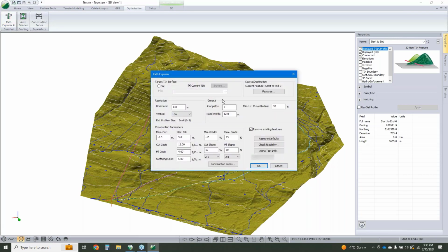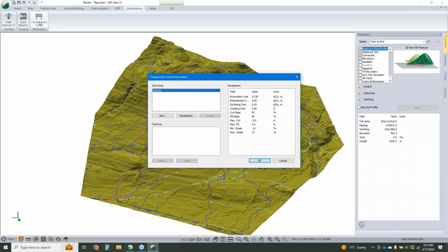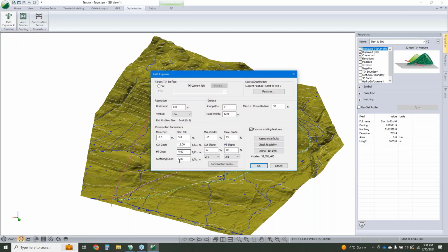So this tool is also looking at earthworks costs. It's looking to minimize your cuts and fills based off of excavated volume. We've got our constraints like grade and radius, and then for feasibility and that excessive amount of fill, we put a limit on how deep we can cut at centerline or how deep we can fill at centerline. So that's this value here. And another thing we'll mention on the fly, these values are the default values that we have here.